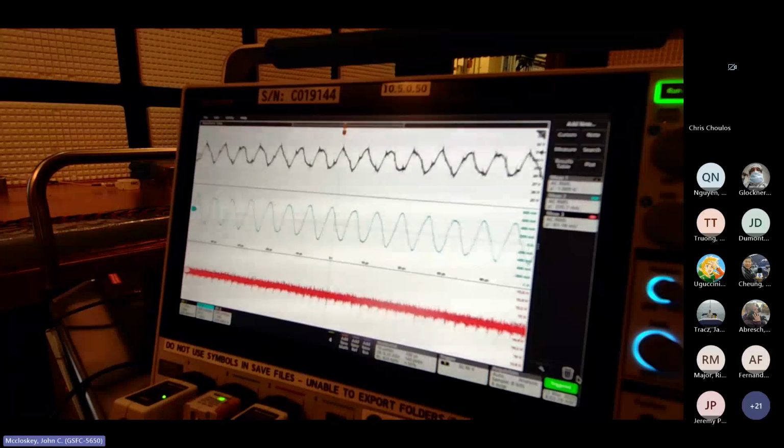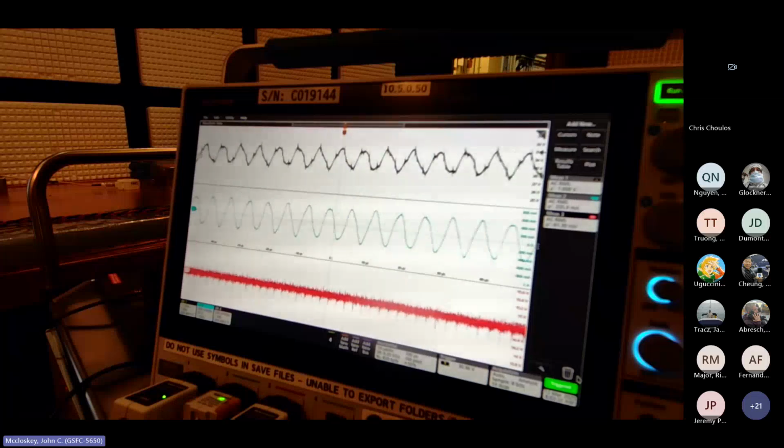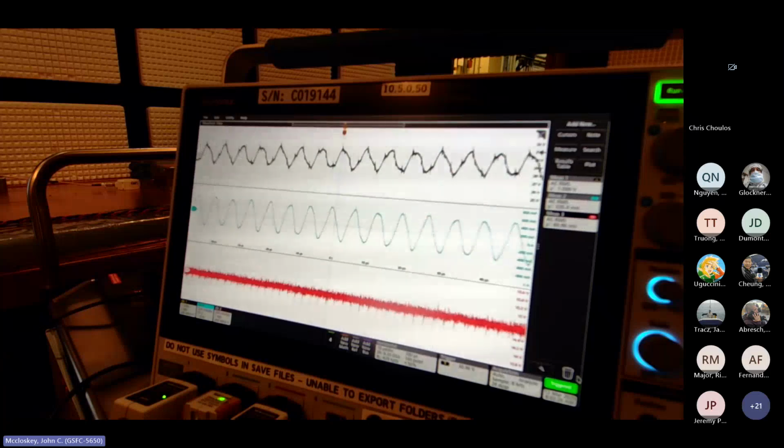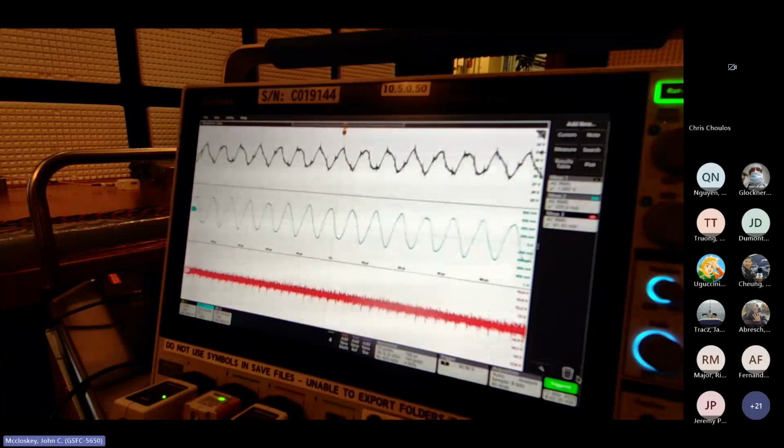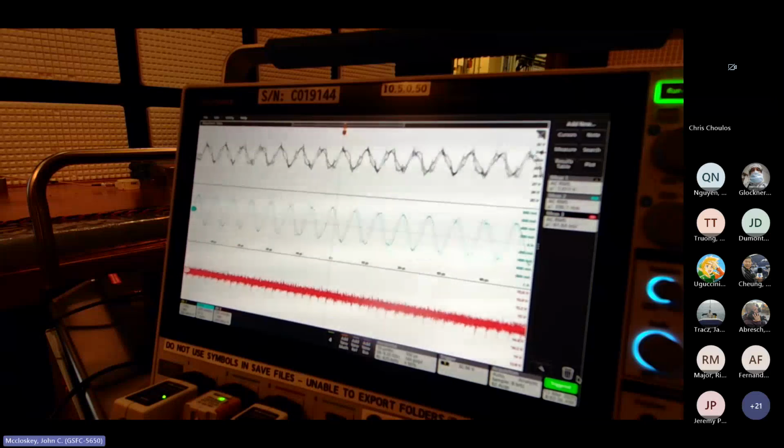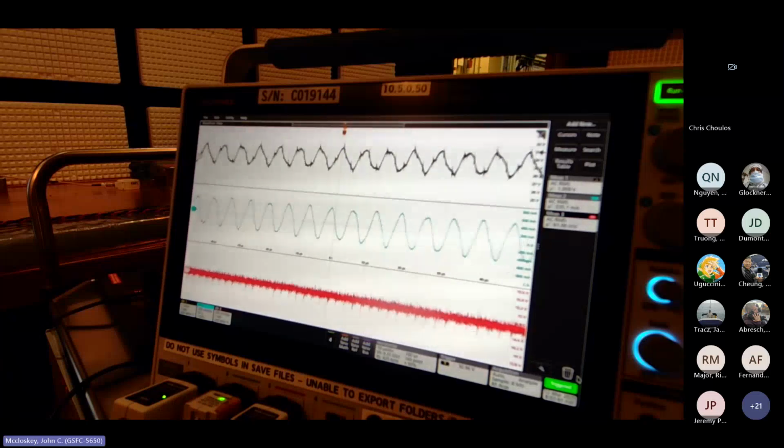Okay, so at 150 kilohertz, we're at minus 20.5 dBm. We're right around a volt with injected signal, and our current is now 335 milliamps RMS, and the secondary's hanging around 62 millivolts still.